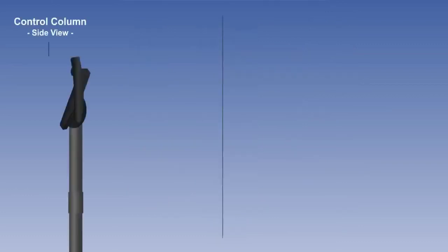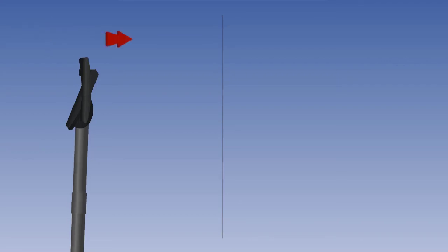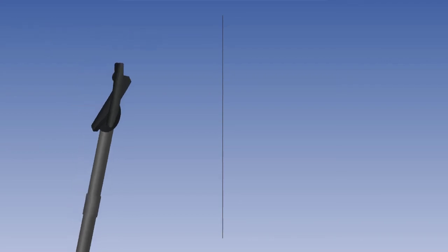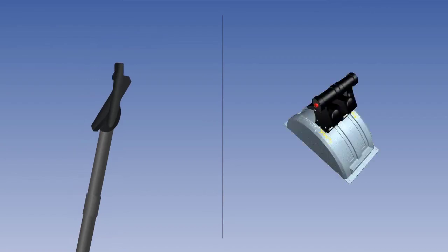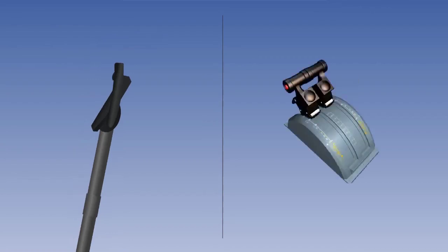A stall protection system differs from the stall warning system only in that it is triggered at a later stage than the stall warning, and it has different outputs. In a traditional aeroplane, we have the stick push, whereas in more modern aeroplanes, we have an output to the auto throttles, which move them to take off go-around thrust.